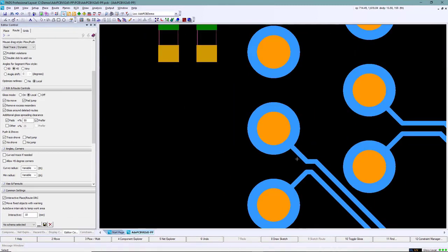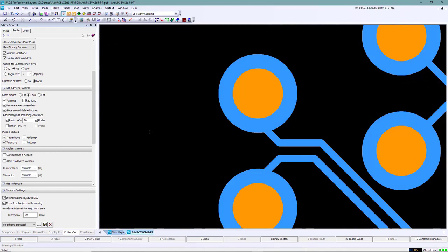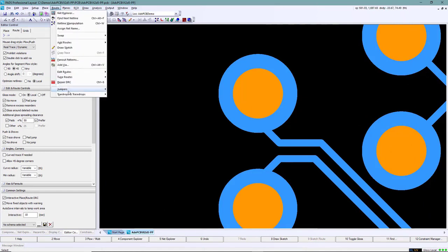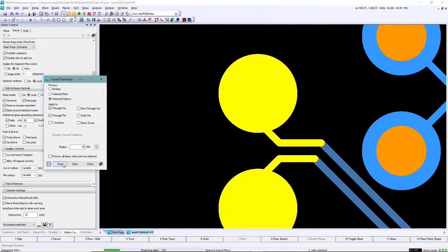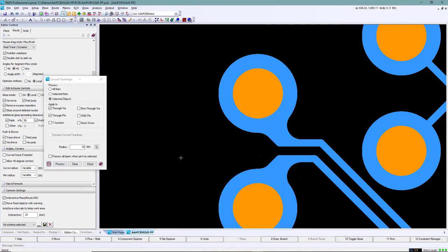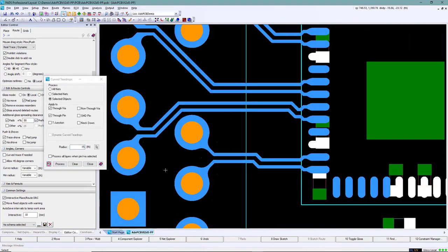We've already covered conventional teardrops, but there are occasions when curved are required in tight spots, or to fix fabrication issues so the manufacturer does not have to modify our designs. Like conventional teardrops, curved can be customized for each situation and applied to only those items selected. Notice how the copper being added is not uniform between each side, but fills in as needed to make a conformal curve.